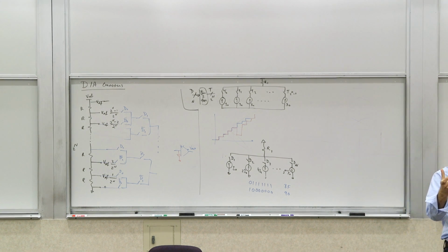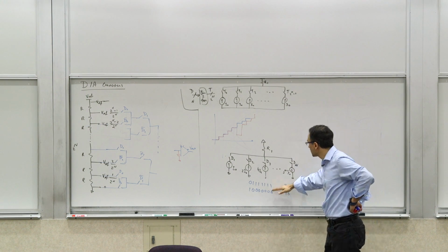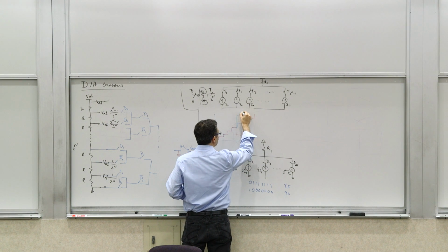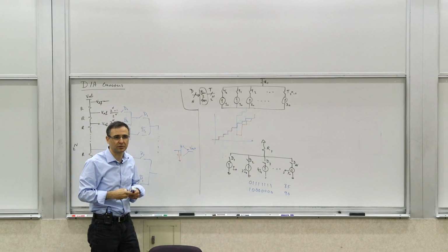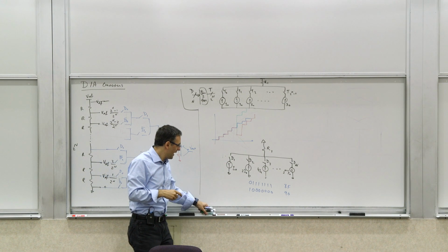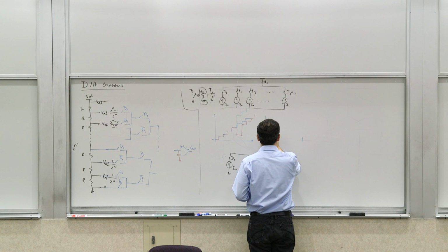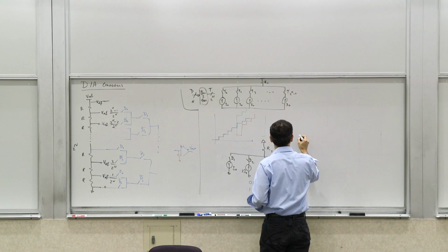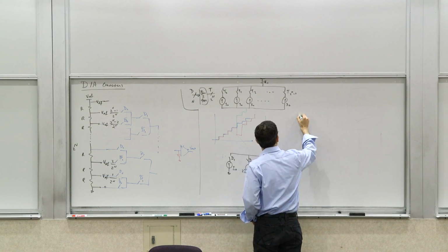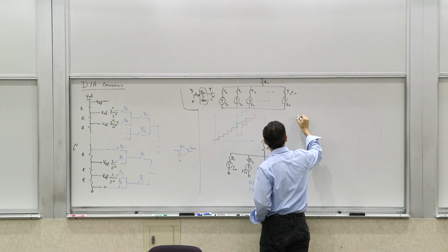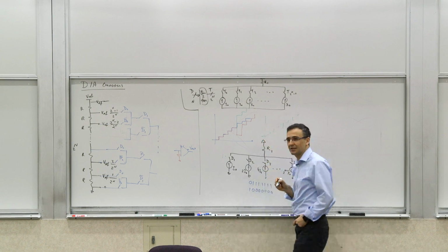The sum of all of those things has to be accurate to the LSB. If there's a small deviation in these, this change can be large. It can be in one direction or it can go in the other direction. It can actually be a big jump here in that direction. What is most pronounced in these things, and you will see it, is this: let's say you go to the full range, to 2 to the n minus 1. You will see the largest jumps here in the middle, and then 2 smaller jumps here, and then 4 smaller ones here, and things of that sort.